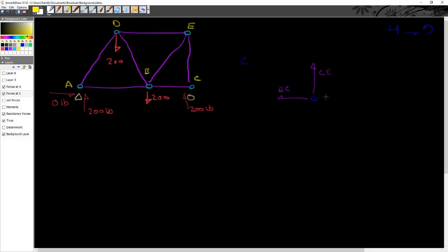And I'm going to put those both into tension, meaning that it's tension pulling on the point C. And it doesn't really matter if we start out in tension or compression. So let me draw my external forces, because if we start out and we assume wrong, we're going to get a negative sign if we always use this convention up here. Okay. So looking at C, what do I have?